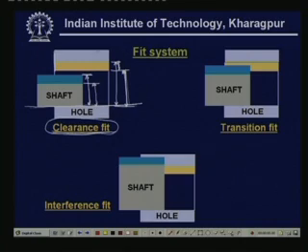See, even if the shaft dimension comes out to be of this size, you can see that it is never touching the hole surface, where all the measurements are made from the same line, because the minimum diameter of the hole is always more than the maximum diameter of the shaft, and that is what we call a clearance fit.